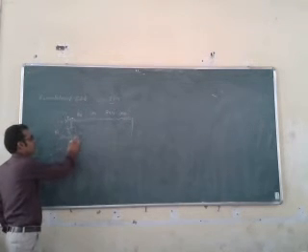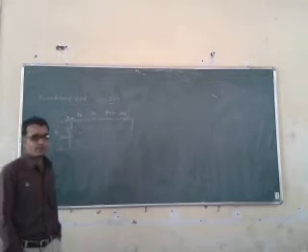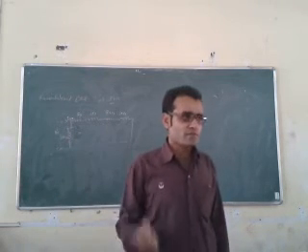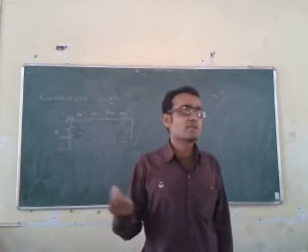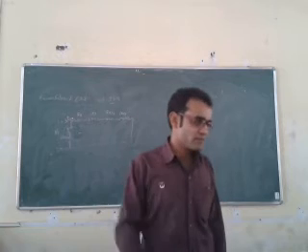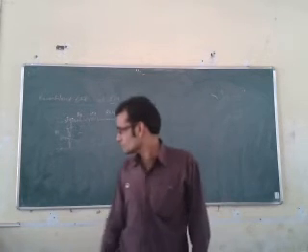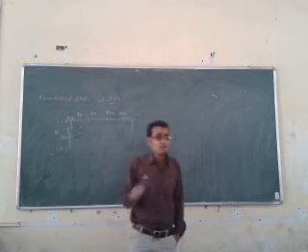And now, the impedance or reactive impedance, the reactance, is also the core reactance, you can say. Or you can say it is the reactance offered by the mutual inductance in between the two windings, one is the stator, another is the rotor.